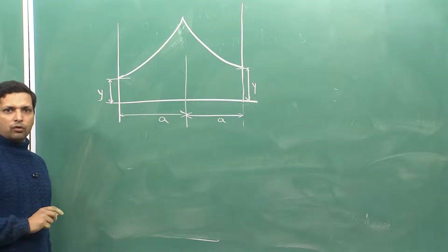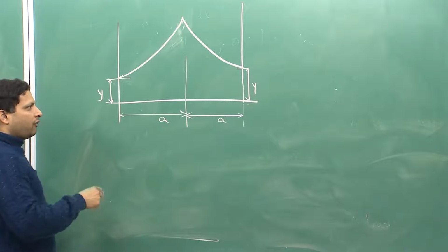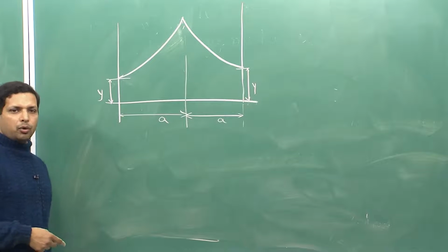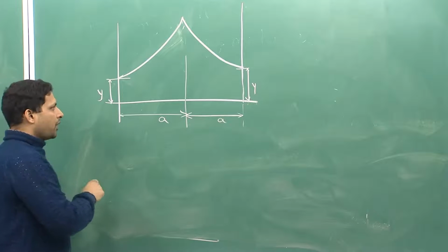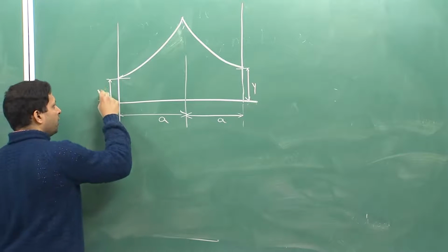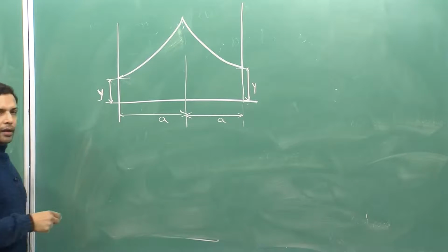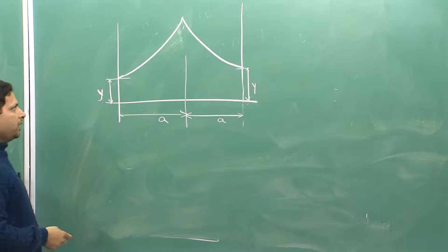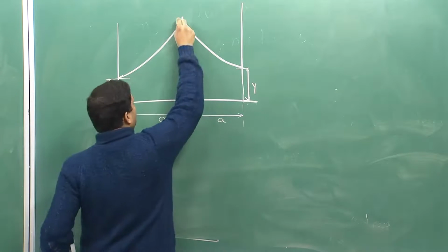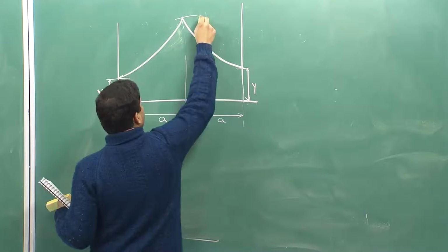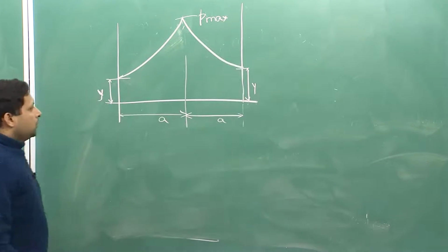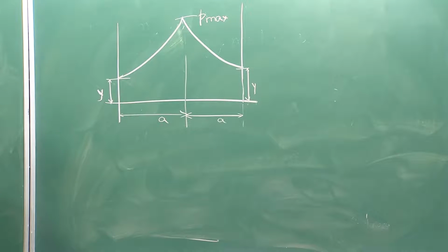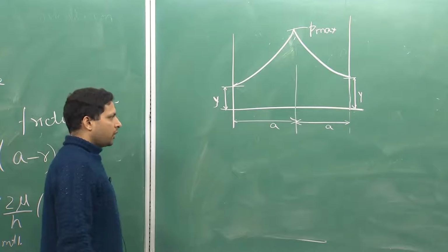That is good, because if it were less than yield strength at any particular point, then that particular point is probably not getting deformed, but that is not happening, and at each and every point your pressure is higher than the yield strength and every point is getting deformed, and in the center you have a maxima. So, this is how the pressure distribution would look like.